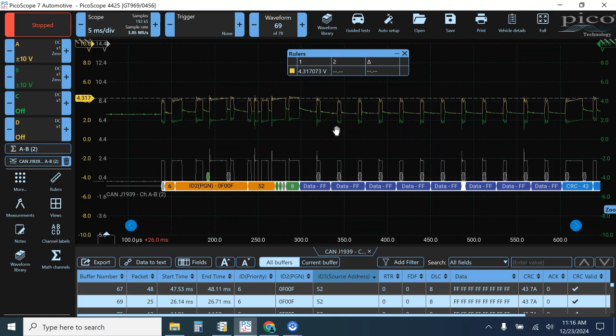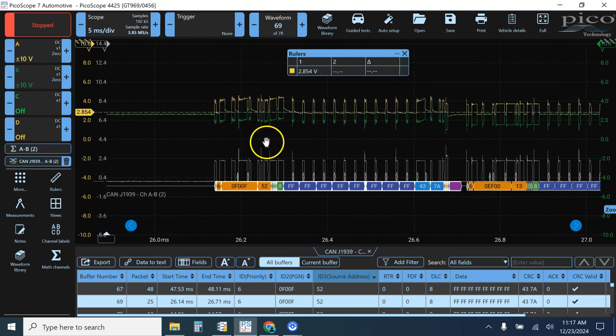On the other controllers on the bus, anytime we go to that recessive state where it should be driving both CAN high and CAN low to 2.5, this knock sensor is trying to drive it a little higher than that. It looks like it's going up to somewhere around 3.2, but the other devices are pulling this back down closer to that 2.5. That appears anywhere we have the knock sensor communicating.